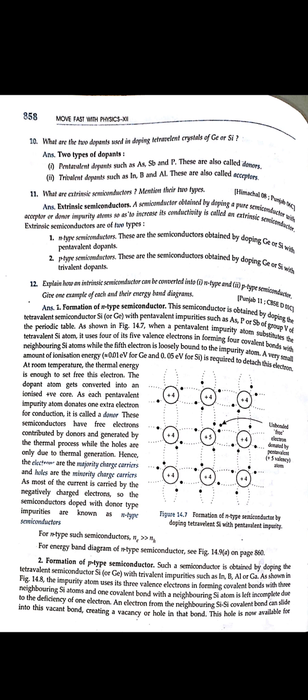Here you can see the structure of the n-type semiconductor, the valence bond model. Whenever you add a pentavalent impurity to the covalent bonds of the silicon structure, we know that silicon is tetravalent, so it will form 4 covalent bonds with 4 electrons of the pentavalent impurity. But the 5th valence electron gets free and moves in the interstitial space of the semiconductor. Due to this extra electron in the interstitial space, it is considered negatively charged.